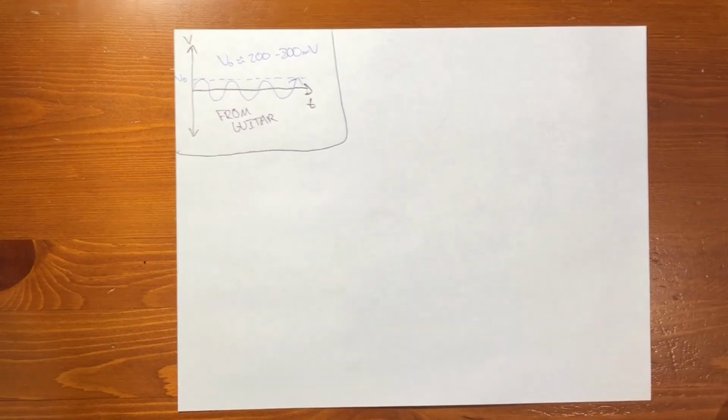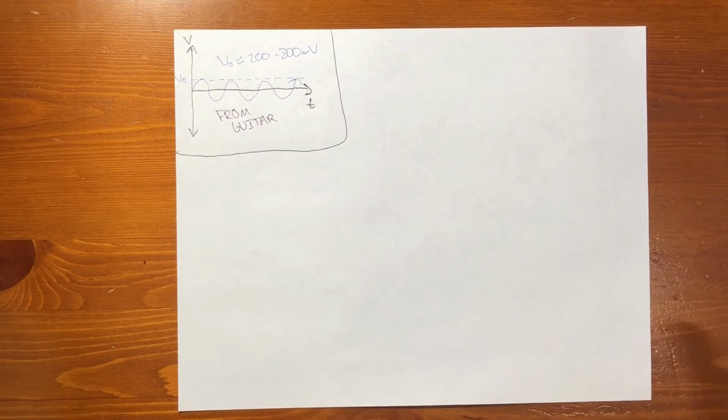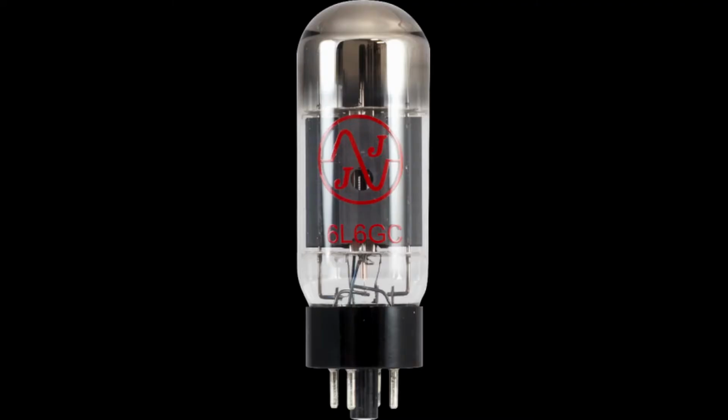From this guitar, we send an alternating current. The current flows both directions. It also has an alternating voltage, right? It's poled one direction, then the other direction, at this frequency that the note is. Nowhere near as powerful as it needs to be to really move that speaker cone and get a loud sound. Therefore, it needs to be amplified, and we will do that using a vacuum tube.